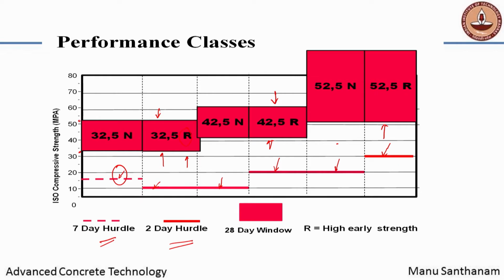And indeed, when you actually take a European cement that is 52.5, you will see that it has a very high fineness. The fineness is typically close to the order of 400 square meters per kilogram, very high fineness. Okay. What is the fineness of typical Indian cements? About 300 square meters per kilogram. Okay. Specific gravities are not all that different. Both cements will have 3.15 or nearabouts 3.15 as a specific gravity.